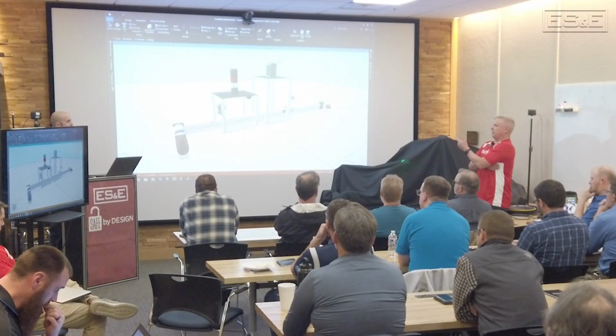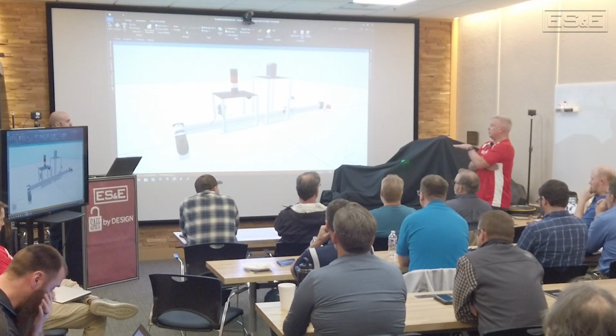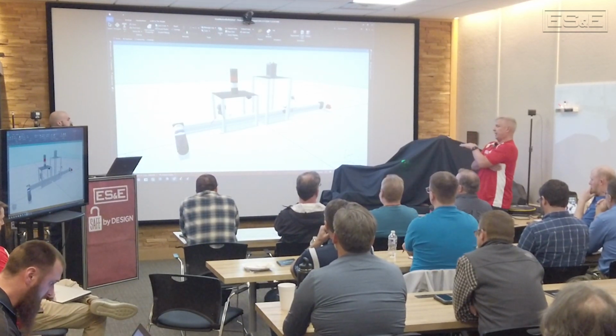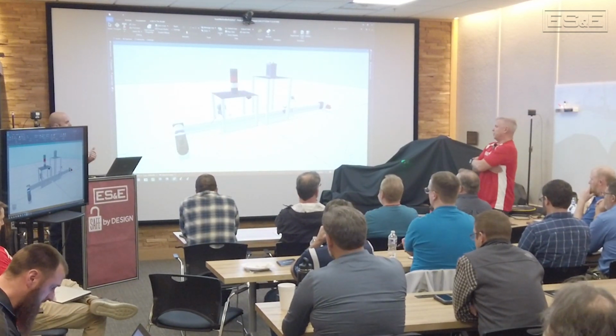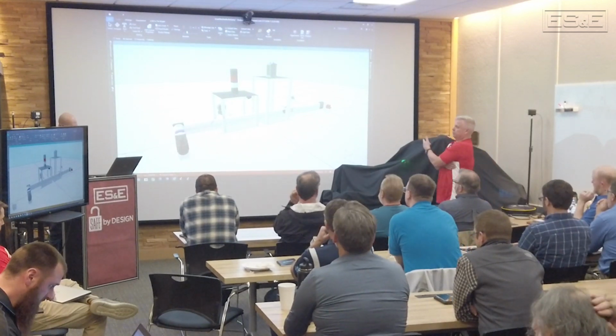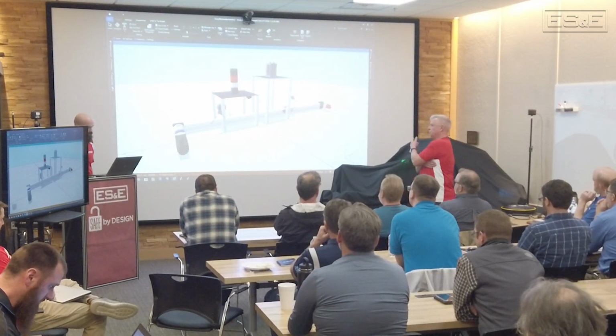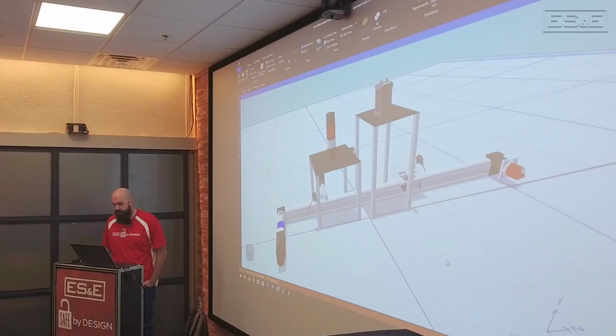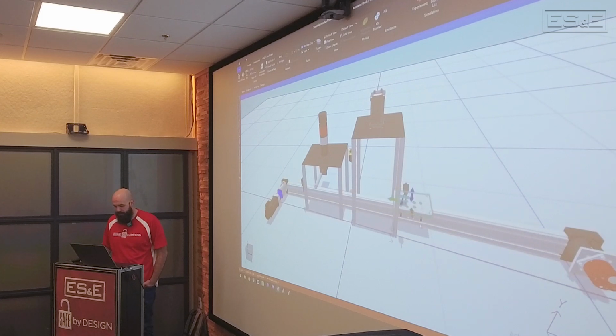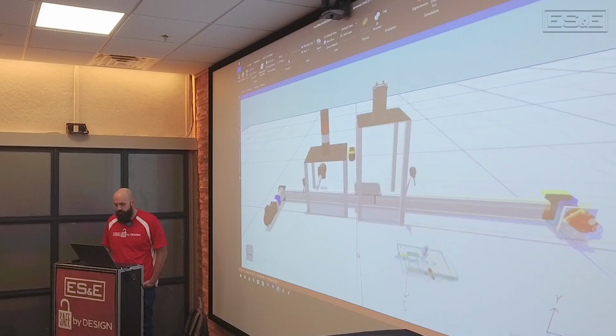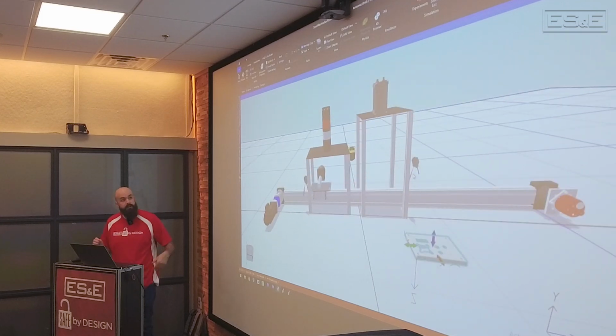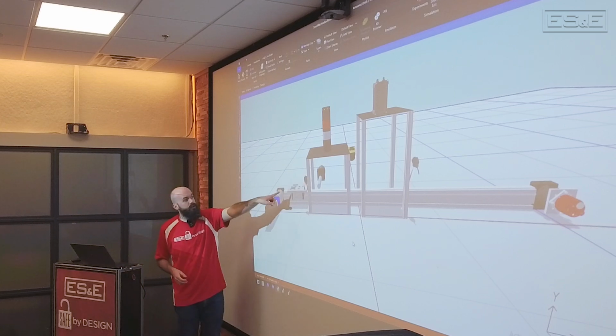But we can treat it like the PE, for instance, block, right? So as soon as we block that tag, you can create the same thing for both the Cognex as well as the Swifty. Absolutely. So I'm just going to take the plate off of that, and you can see when I remove the plate, the photo eye gets unblocked, and then what you'll see is when a new plate comes on,